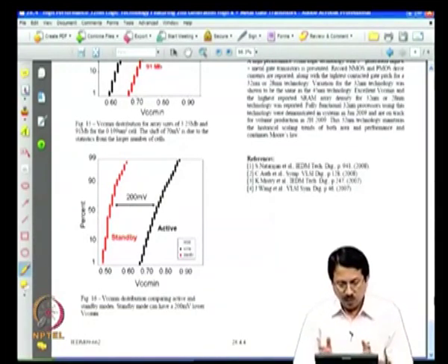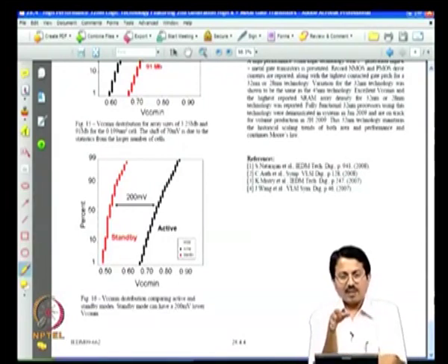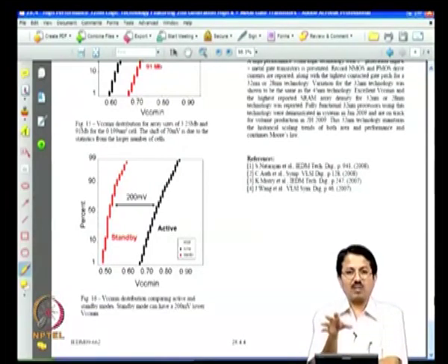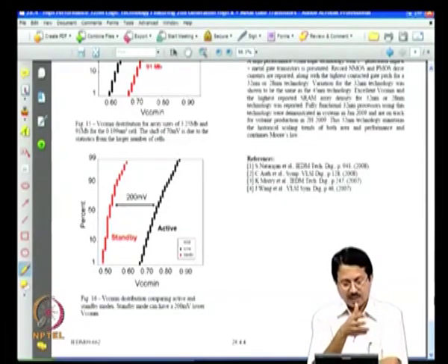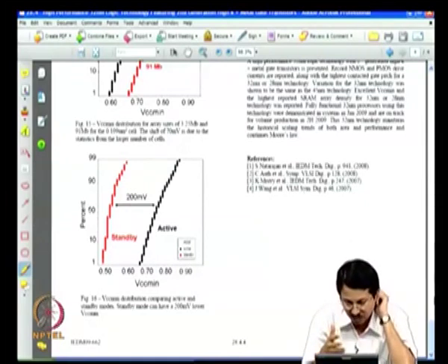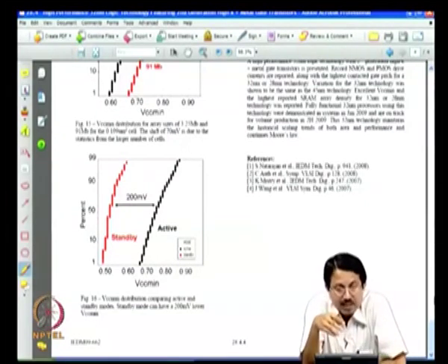So, what we have been able to do in this lecture is really to look at representative CMOS logic technologies, not memory technology. These technologies are not for DRAM fabrication, not for flash memory fabrication, not for even SRAM fabrication, but to make very high performance microprocessors, okay. So, their performance is the key. You want to make the transistor which gives the lowest delay, and various techniques we have seen. All the source drain engineering, channel engineering is consistently used in all these transistors, and as we have continued to scale the technologies, we have transitioned from silicon oxide to high K gate dielectrics to metal gates, and so on and so forth.